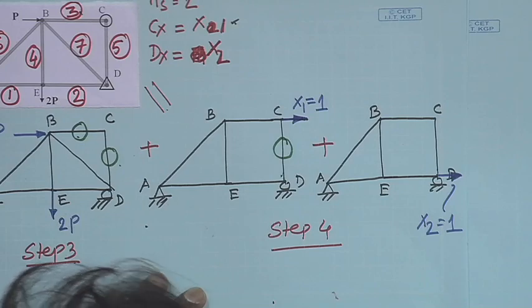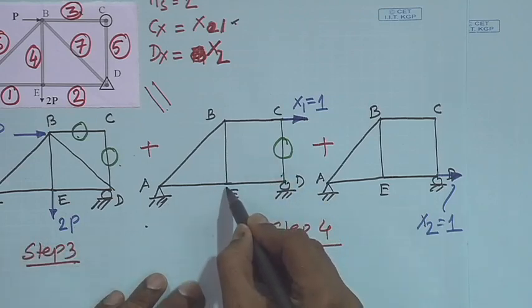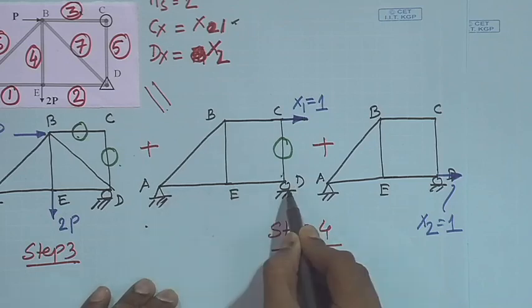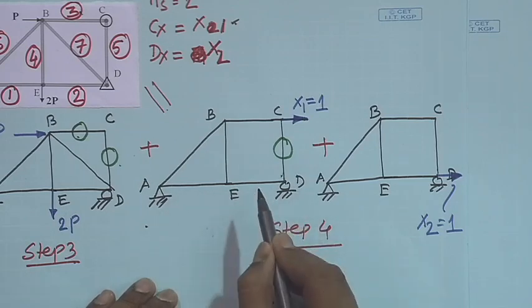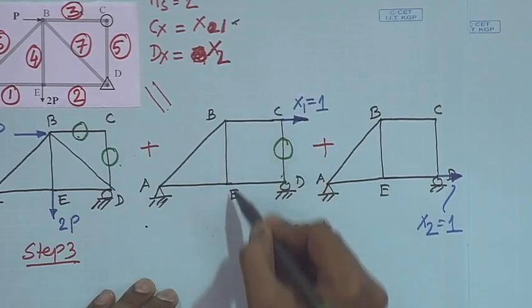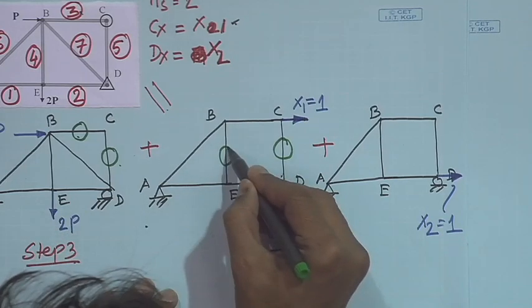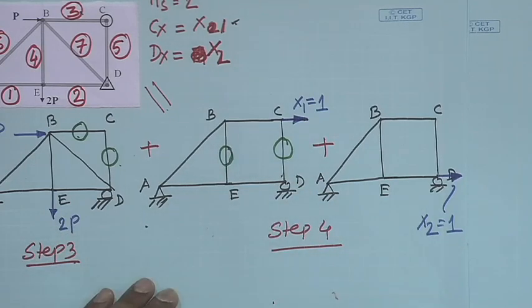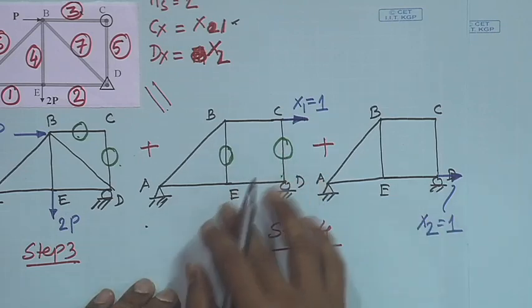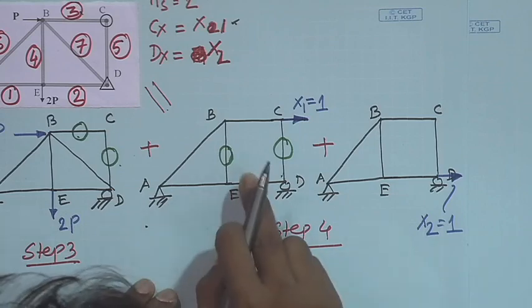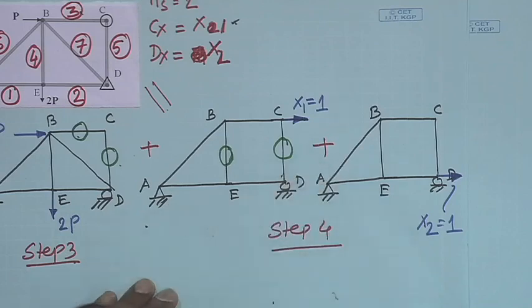Now, similarly, if you see joint E here, now the AE and ED, their forces are horizontal and they may balance each other, but there is no other force to balance the vertical force in member BE. So, this has to be a zero force member. Okay. Now, so at least we can say that these are zero force members. Okay. Member, so what are those? Member number 4 and then member number 5, they are zero force members.